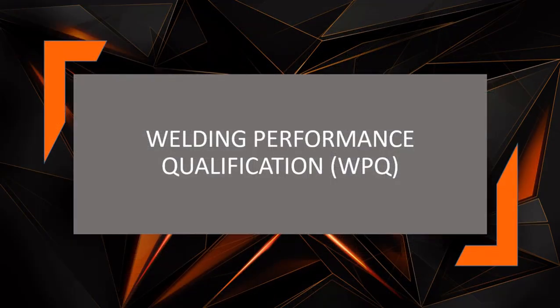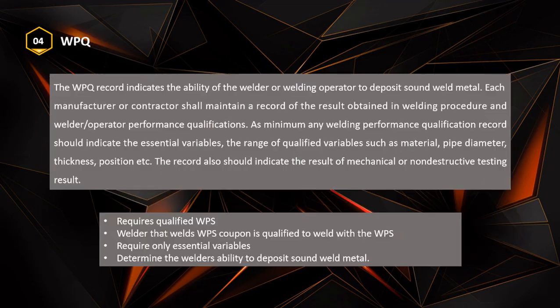Welding Performance Qualification, WPQ. The WPQ record indicates the ability of the welder or welding operator to deposit sound weld metal. Each manufacturer or contractor shall maintain a record of the result obtained in welding procedure and welder/operator performance qualifications.